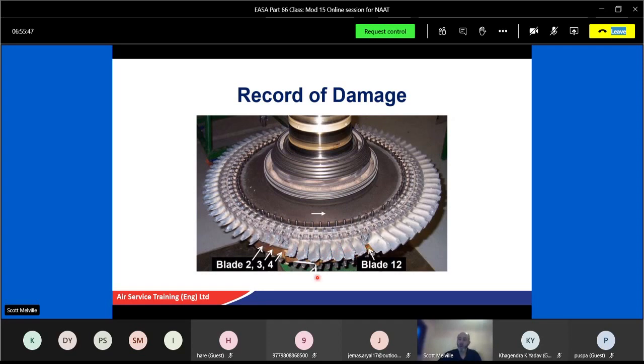But again, wherever you number that from, you probably wouldn't find a number on the actual blades. You tend not to find that. All you can use as a reference is maybe a point on the disc, or you might find a mark, you know, maybe a hot spot, and use that as a reference point. And then you'll be able to know how many turbine blades are on there. Okay. But if in doubt, just put how many blades were found to be damaged. That's what I used to do.